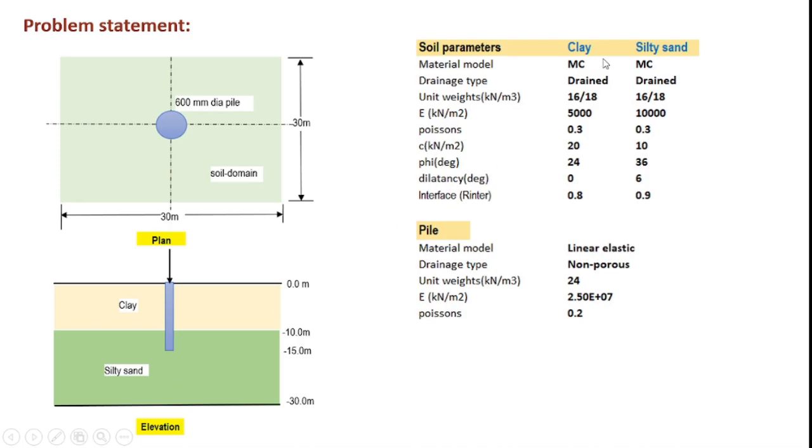The properties of both the clay and the silty sand strata are given here, and for both the soils we use the Mohr-Coulomb material model for the analysis, and the pile will be modeled using linear elastic non-porous material. So let us start the PLAXIS.